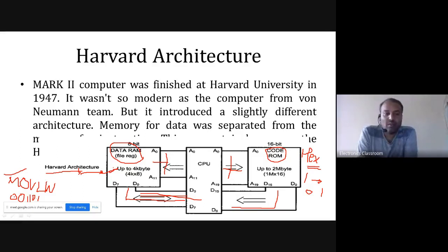A simplified version of this, for example, 34h, is the decoded value for the sake of human understanding. The human language is MOVLW, the machine language is 00011100, but for simplicity we have decoded this into the hexadecimal number system.